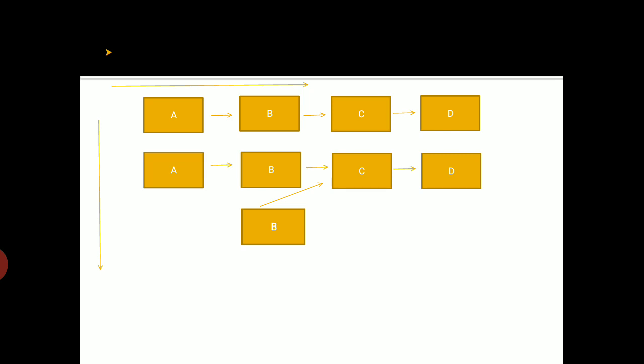Whereas if we see the downward falling diagram, we can see here very clearly that it is A, B, B, B, C, C and D, D. What does that tell us? That means of A type of machines there are 2 machines, B type of machines there are 3 machines, C type of machines there are 2, and D type of machines are available in the quantity of 2. That means the arrangement is according to process layout. Same functioning machines are kept together. A, B, C, and D.